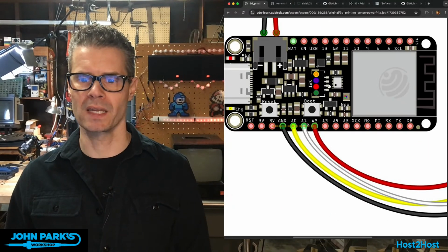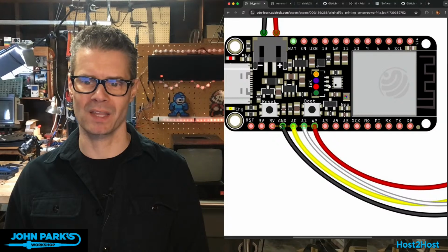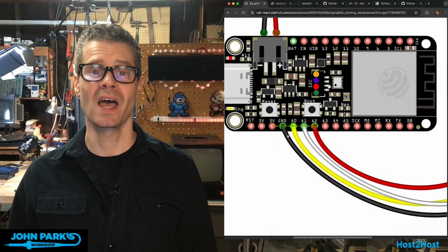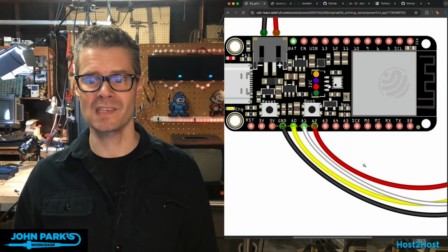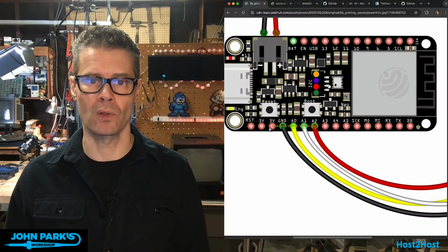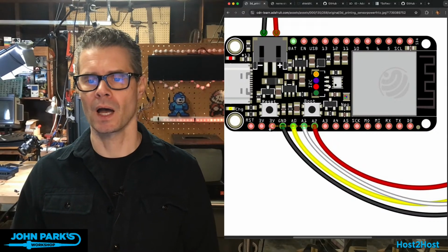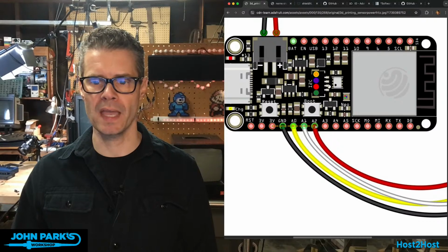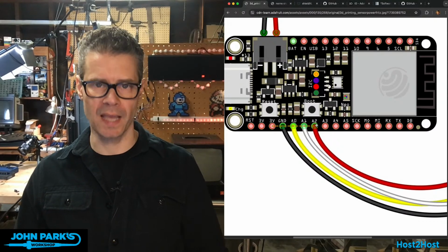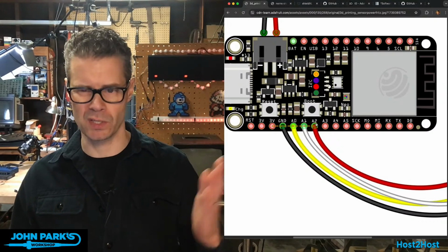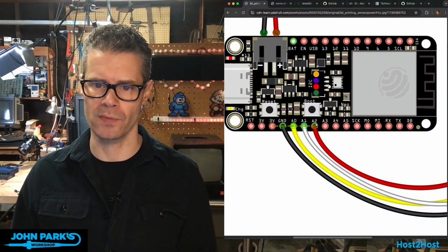Notice where they're going. Oh, and I need to fix something in my schematic that's causing that dotted line, because I used to be running my VCC line just to the 3-volt line on the Feather. I've now moved that over to the A2 pin, which I'm setting high to provide power. It's essentially the same, and this is a low current draw thing, so that works fine.